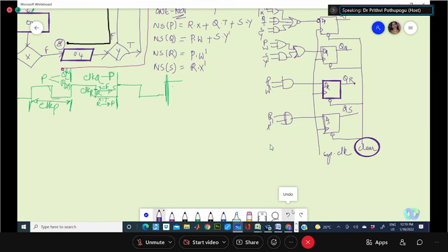But the other way around, any number of states you can include. The only thing is that for each state, one flip-flop gets added. Okay, 10, 20 states also you can add, but the complexity that increases is that the number of flip-flops in your design grows with each state, because this is directly related to the number of states. So your overall circuit looks something like this.